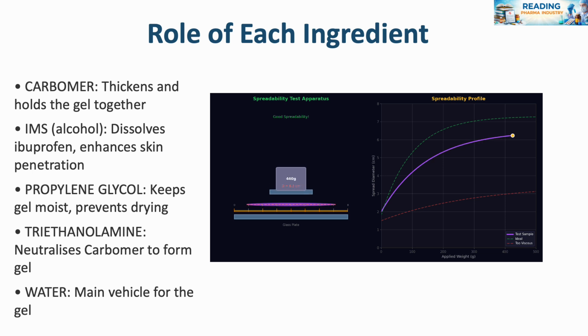You can test or assess the gel using viscosity measurements, and that will give us the behavior of the gel as we apply shear. And you can see that it will have the same kind of behavior where we have the pseudoplastic effect. That means when we apply shear, the gel starts to thin, so we'll have a thinning effect.